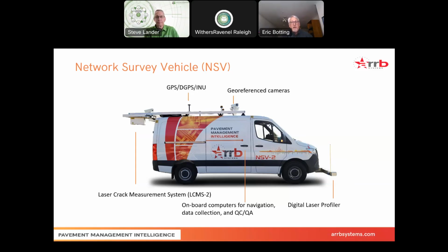What has recently been done to get around these things is an ASTM standard, E3303, which is totally automated, and it looks for a percent cracking in each frame. So if you want to do monitoring from year to year, it's very easy to compare the two. You can do it visually, you can do it through databases.